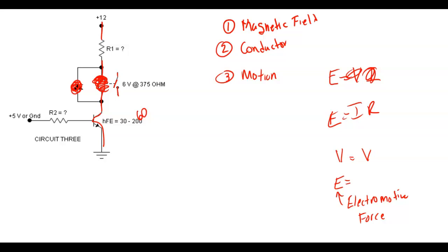If that transistor is sitting there dropping 60 volts and you push current back into it backwards, you're going to pop that thing. That's why diodes have what we call a PIV rating, how much they can guarantee they can block when reverse biased. Transistors have breakover voltages. This would be called the voltage collector to emitter, with an O for base open. If the base is open, the transistor's turned off, right? If you exceed these breakover voltages, there's a high probability that solid state device is going to be damaged.